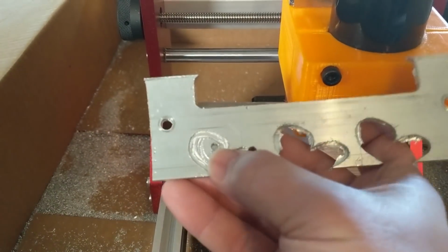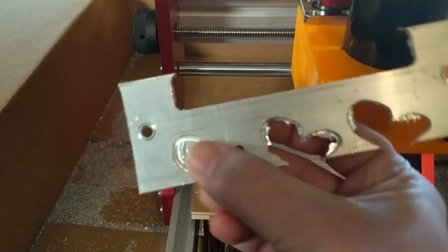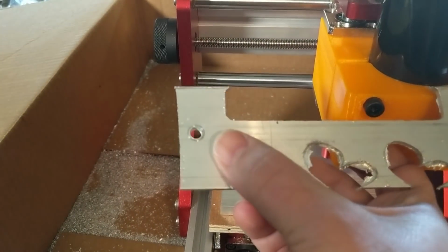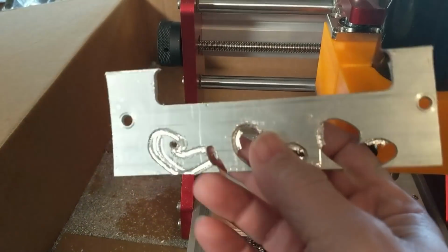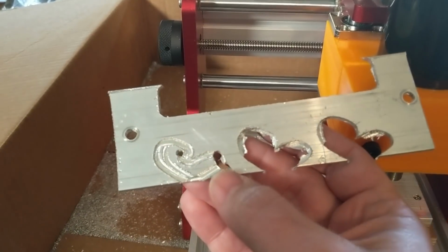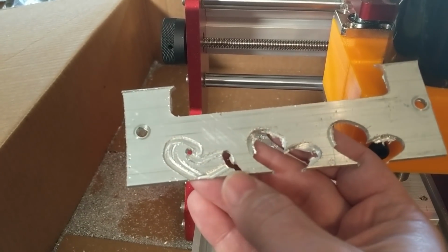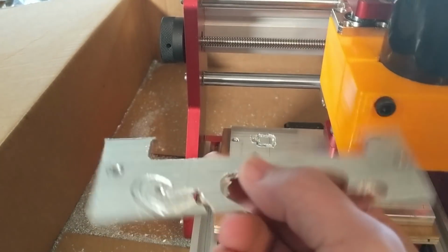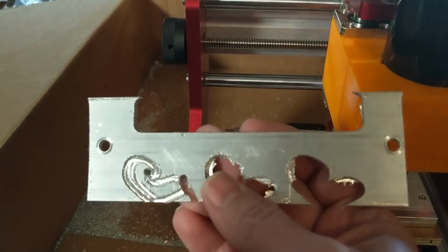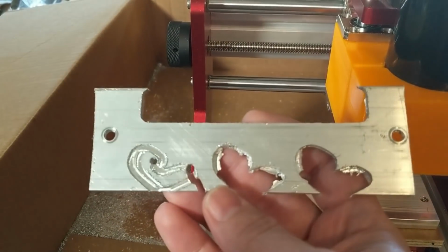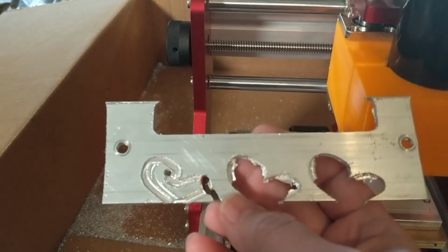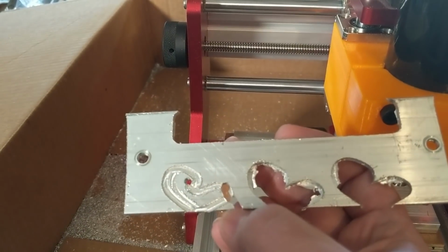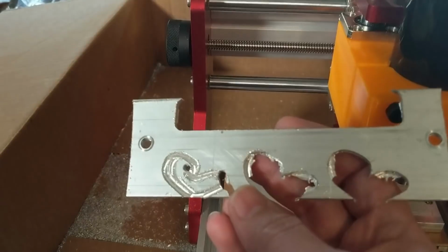And yeah, I kind of haven't been showing you guys all the tribulations and trials that I've been going through, but here's a cut where the motor was moving on me, and that's why I had to increase the torque on those stepper motors, because you can see that cut path changed. And once I got the torque up on the stepper motors, I sent a job wrong with it zeroed up in the air, so it dived way down into the material. It was cutting all the way through that material in a single pass, which is darn impressive, that spindle can cut through 3mm of aluminum in a single pass. But you can see that the stepper motors just couldn't keep up. See that funky path was the stepper motors skipping and just being dragged through the aluminum.